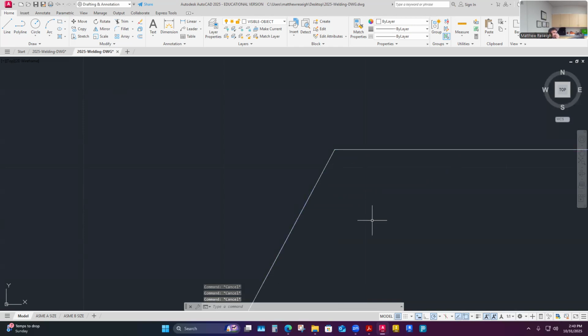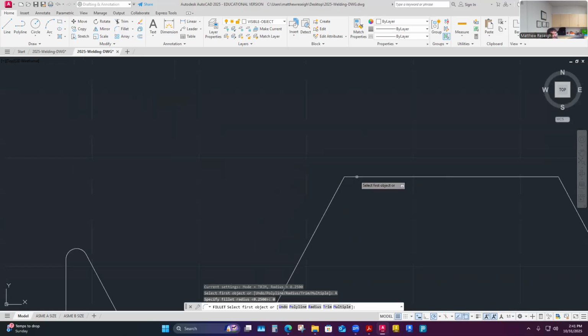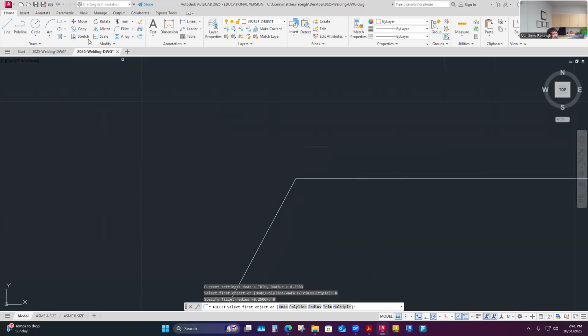Did I do some trimming already? Usually your fillet command radius default is going to be 0. I must have done some other drawing today, and so maybe it's remembering. But usually if you haven't done any fillet commands, the default is 0 for the radius. And so you might think, I'm selecting fillet, I'm selecting this geometry and this geometry, and then it just boots you out of the command like it's done. It just did, and you're like, what the heck? I didn't do a fillet, and then you go back and do that again and again and again. This is an annoying command. I don't know why they haven't fixed this in all these years. Everybody that's run CAD gets used to this, but the default is 0 for fillets for some stupid reason.